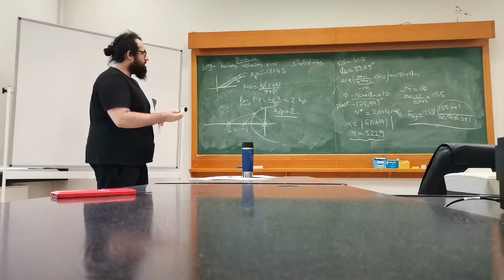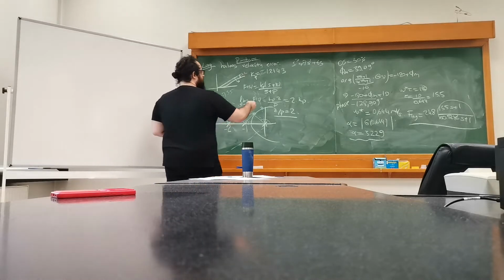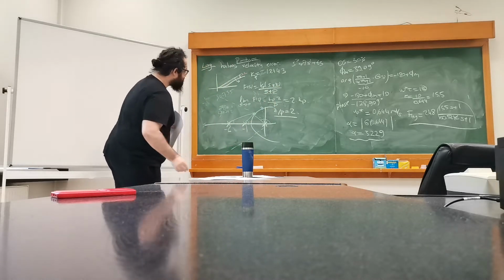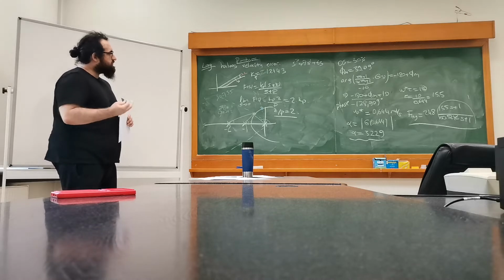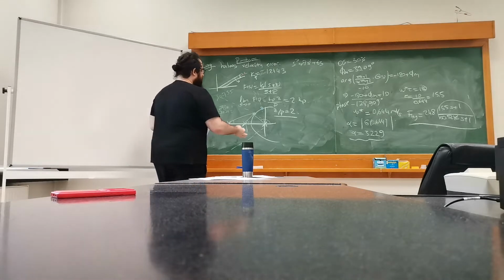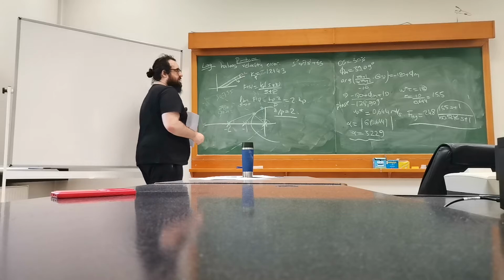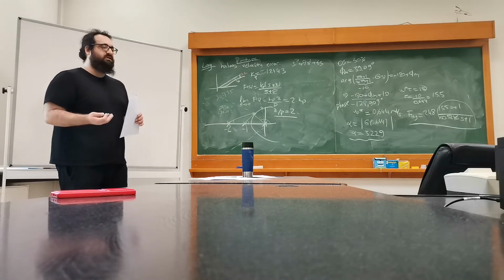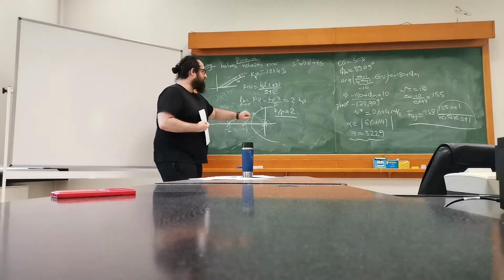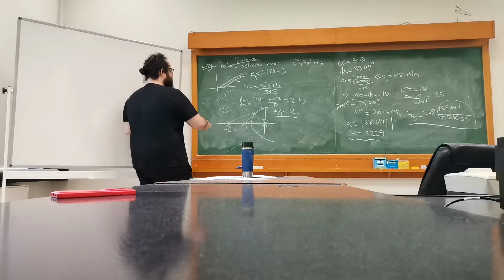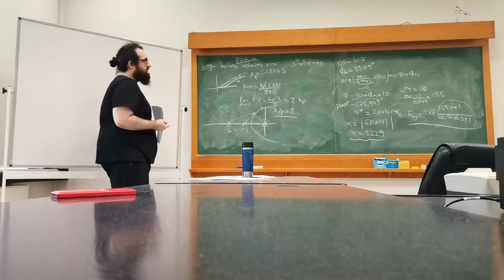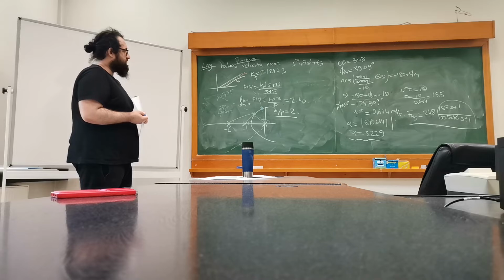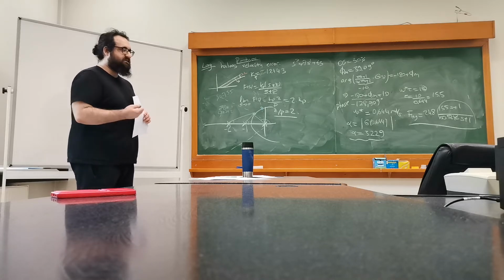And, well, if I'm adding poles and zeros, which I'm doing here, I'm adding just one pole and another 0. I don't really want to change, basically, the overall angle condition on the root locus. Because if I do that, my whole behavior will change because it will not correspond to this point anymore. So it should have roughly the same sum in terms of the angles. So what is the best point to introduce a pole and a 0? That's basically the question in this timeline.